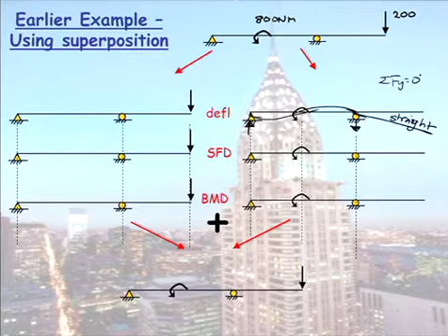They are a couple opposing the moment. The moment's trying to rotate it one way, and these 2 forces are stopping it. I've got to make sure my arms are going the right way. So shear force diagram, I step up, I move across, and I come down. This is a moment, it doesn't affect the shear force diagram.